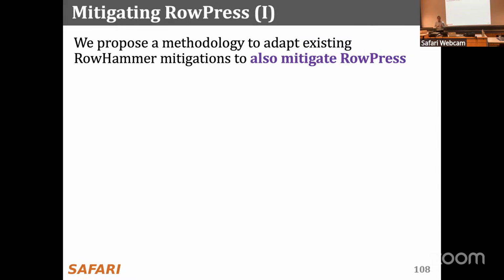So I think we proposed 4 mitigations. We described one of them in more detail, but one mitigation is, of course, changing the DRAM chip somehow, such that a row doesn't become active too long, right? If you decouple the row from the row buffer, that could be one solution. That introduces some downsides, but it's possible to do it. I think there's more work to be done in that area also.